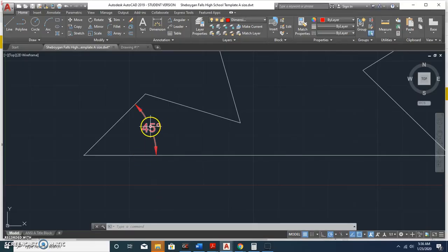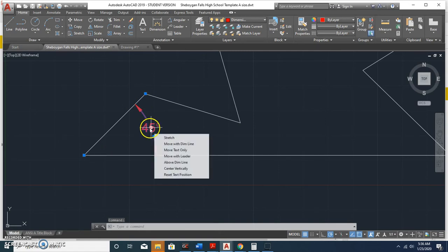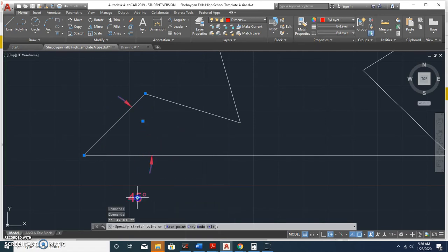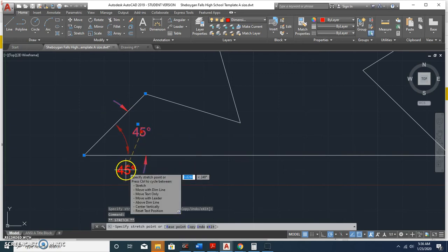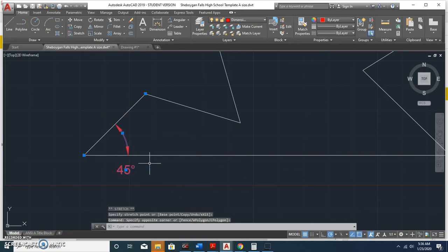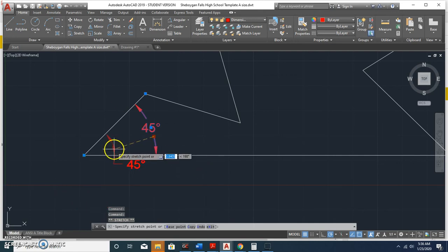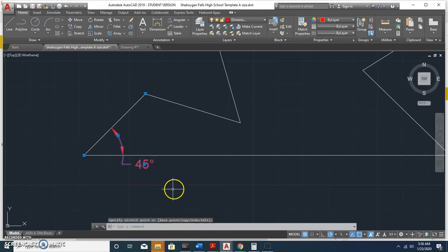Okay, so I can come back here and click on this, and then I get all these blue dots, which are called the grips. I'm going to take this middle grip, bring it down, and then move it. I can bring it back in here, move it till I see what I like. All right. Now Control Z is my undo too. Notice I grab that other grip and see how it acts a little bit different, and I kind of like that a little bit better. All right, so get in the habit: Control Z is my undo.